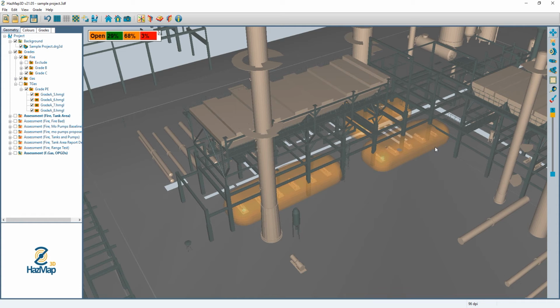This is particularly interesting and useful sometimes in that I may know for a given area that I'm probably going to have a flame detector on one of these posts, but I may not know what elevation and what post specifically I want to attach the flame detector to, or what might give me the best coverage. And the Flame Detector Optimizer tool lets me rapidly go through several iterations and lets the computer tell me which one it thinks is better or better suited to the task.